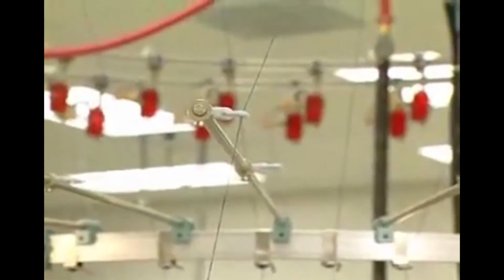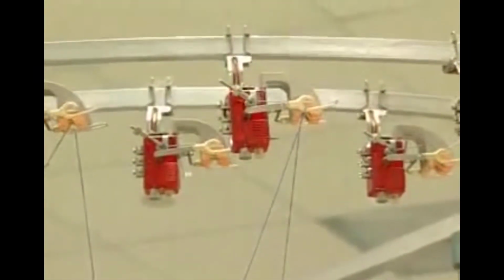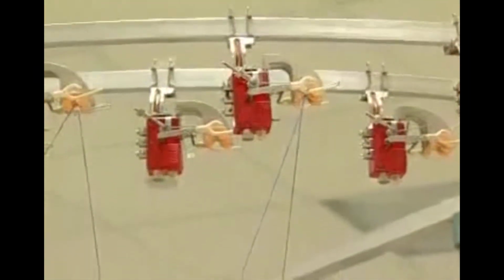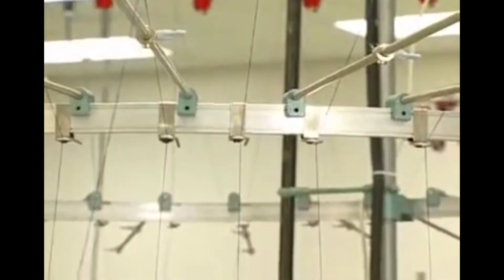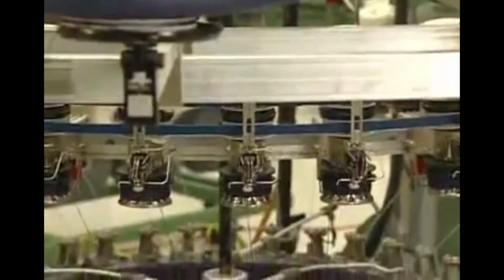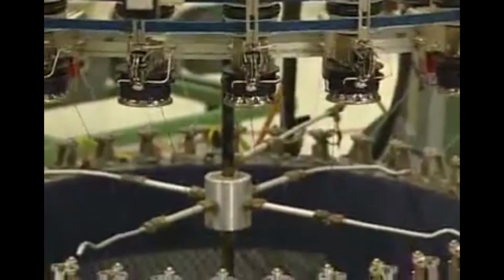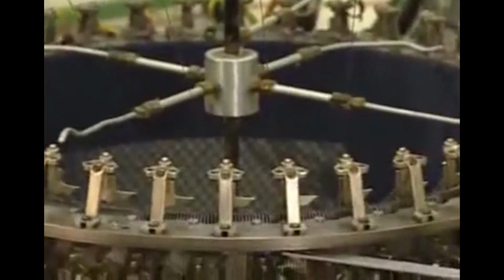Whether the creel is at the side or top, the principles for circular knitting are the same. Fed from above the knitting elements, yarns move from the yarn supply, or creel, through guides to stop-motion controls above the machine, then back down through tension controls and yarn feeding devices to the knitting elements. Quality products can be produced only when stop-motion and yarn feeding functions are properly set.